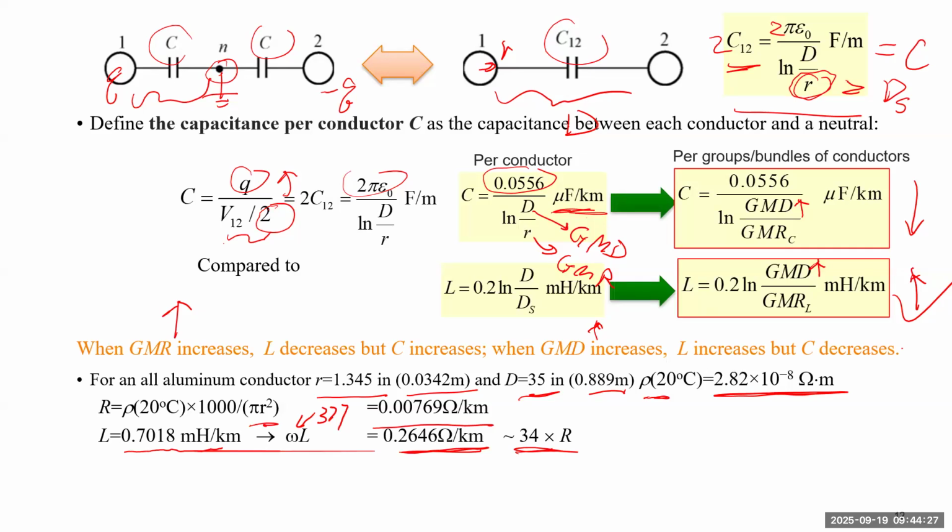Okay, so assume you make this transmission line, and you model this line as a single impedance. The resistance is very small. It's almost ignorable compared to the reactance of the line. So the real part is very small, and the impedance can basically be treated as a purely imaginary number.